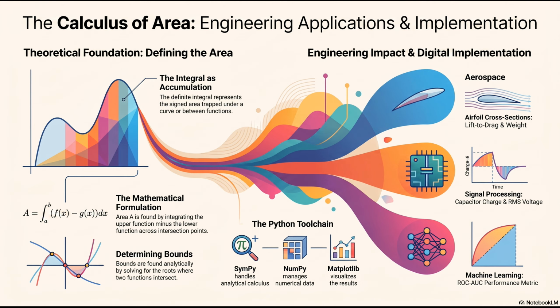That makes a lot of sense. And furthermore, squaring naturally gives heavier weight to the extreme peaks of the voltage wave, which physically aligns with how power actually dissipates as heat in a resistor. Oh, that's elegant. Once you integrate that squared curve to find the total area, you divide it by time to get the average, and then you take the square root of the whole thing to bring the units back to normal voltage. That is your RMS. It's just a mathematically flawless way to measure a fluctuating bidirectional force. The consistency of the logic across entirely different scientific fields is amazing.